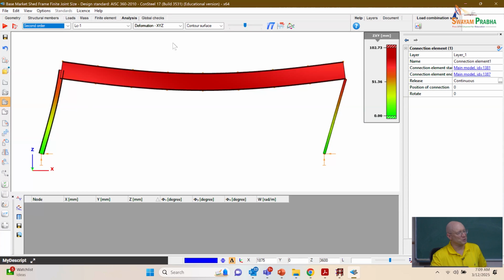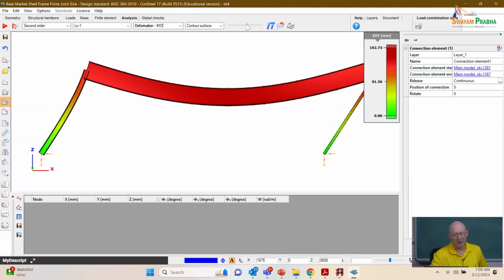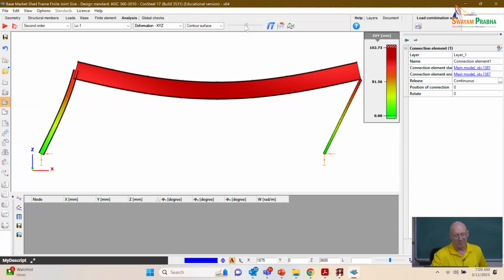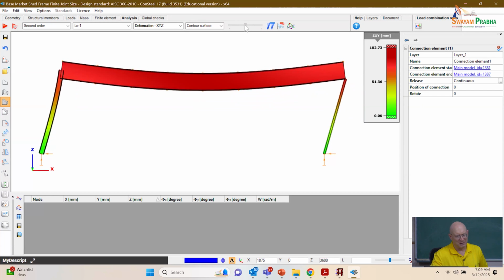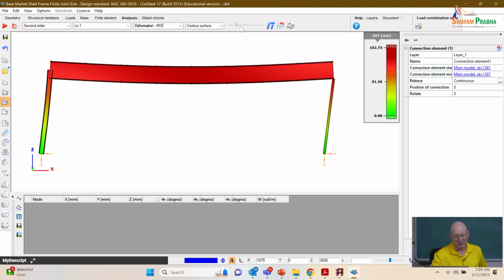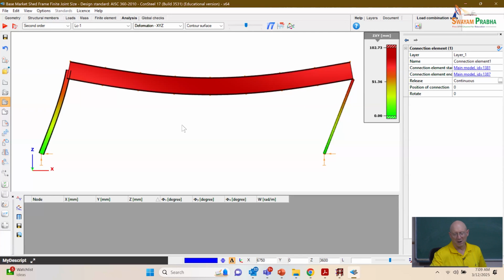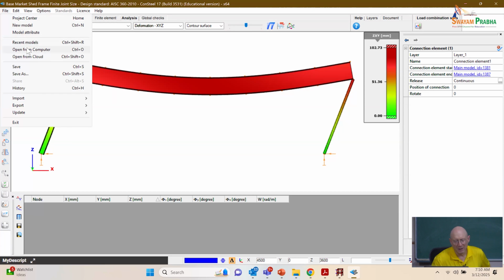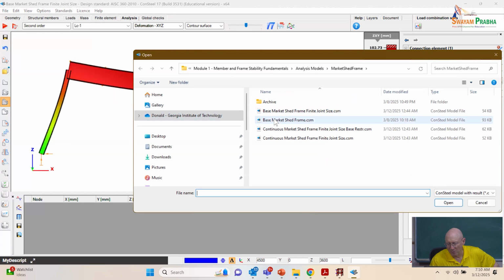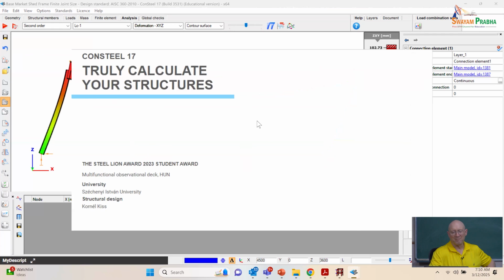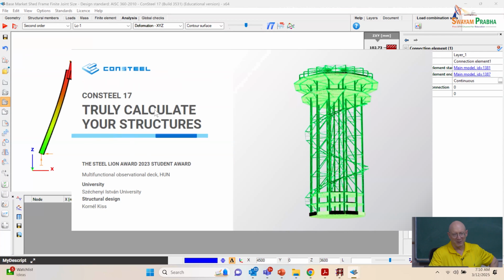It's not the torsion. We could look at a buckling solution out of plane, and there might be some things going on there, but here I'm trying to get you to focus on this in-plane response that I'm trying to highlight. So this is the way this model is working now. Let me bring up a model that doesn't have this, and that might help you in thinking through it.